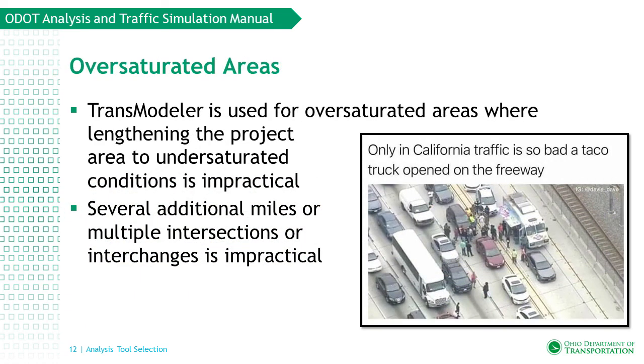When project areas are oversaturated and it is impractical to expand the analysis limits to undersaturated areas, Transmodeler should be used. Lengthening the project area by several miles or multiple intersections is considered impractical.